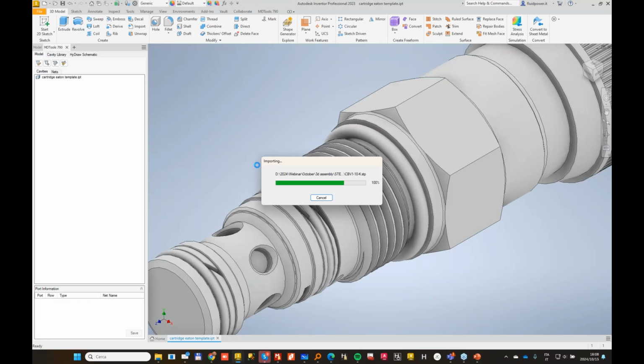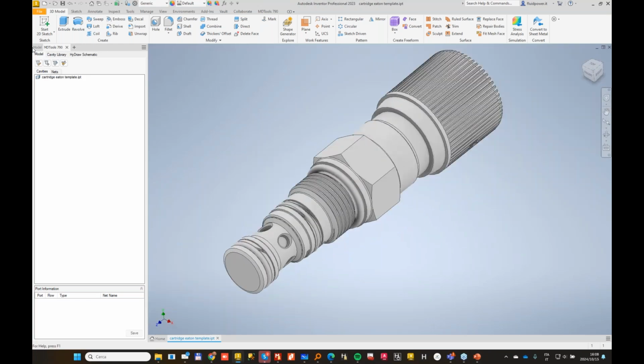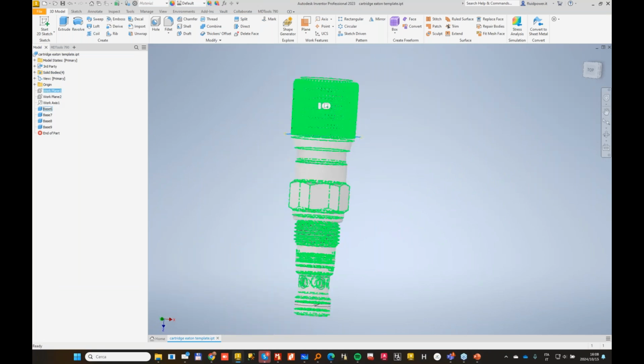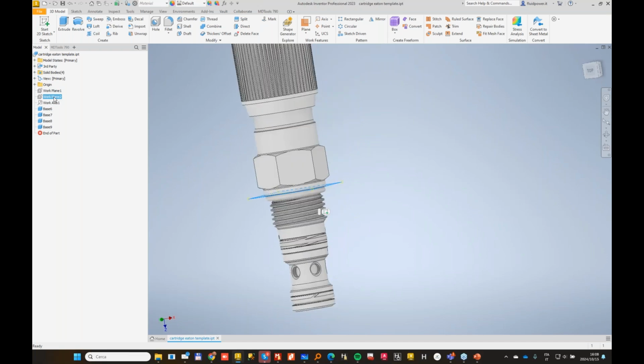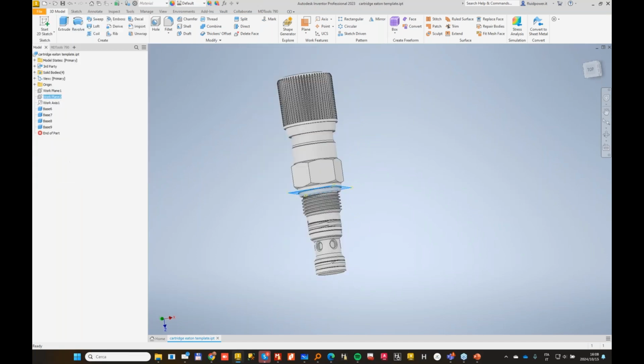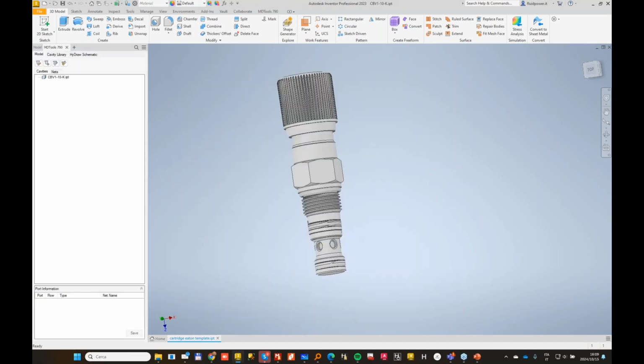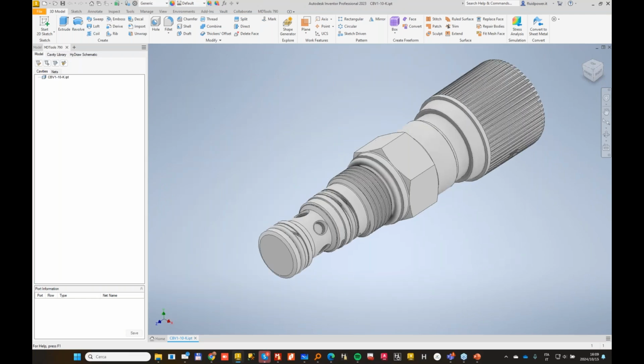And if the 3D model has been made the same way, as you can see now, the top face is there, but really it's not needed. The bottom face is the same. Then here we can just do a save as again and save with a new name, which is the K. So without wasting time in specifying again the constraint, we can reuse what we already had by importing a new geometry.